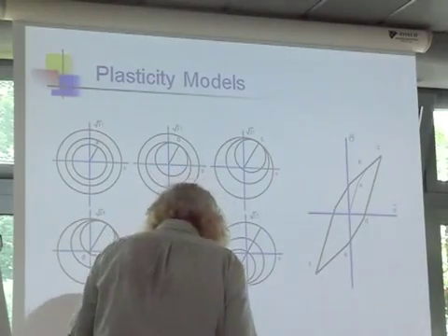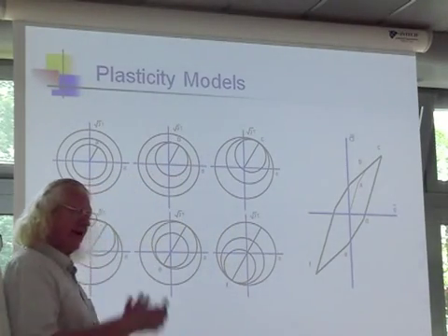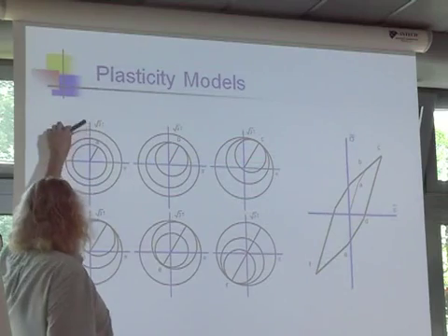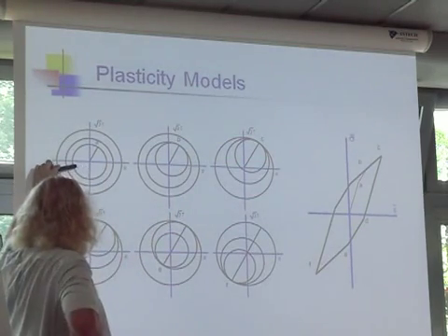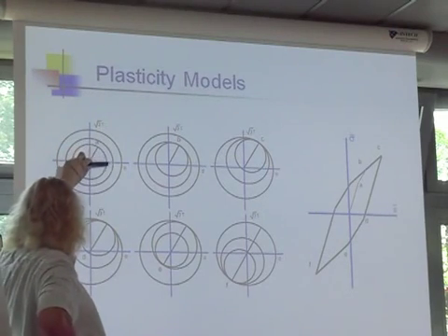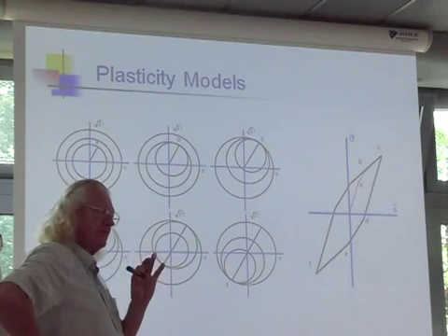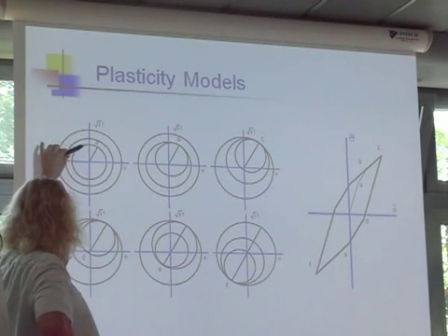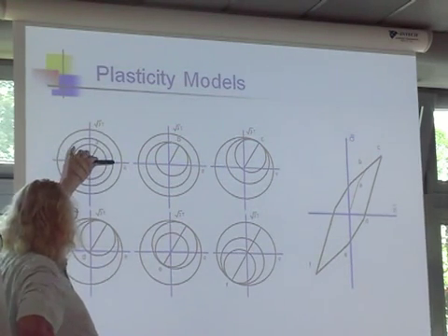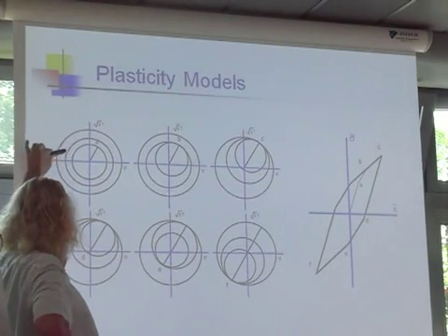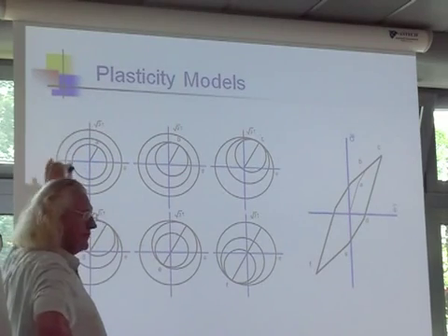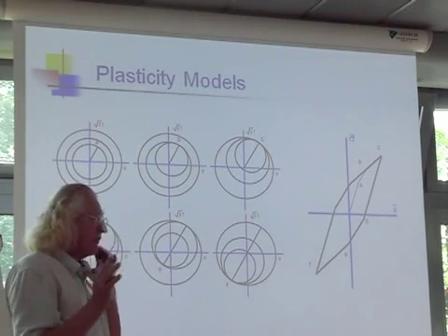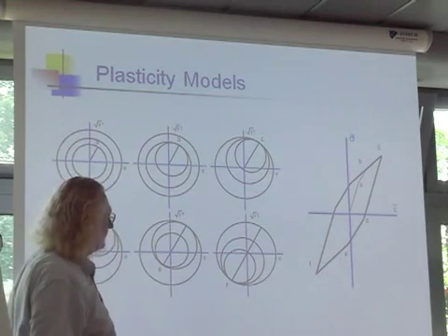So now think about, I have the material. And now I talked about yield surfaces, but I could have these funny little surfaces. Remember, this is just the tension stress, and this is the shear stress acting on the plane. And this represents the combination of stresses that are required to yield the material. But the yield surface concept works for other strains. So for example, this is the combination of stresses that cause initial yielding. This is the combination of stresses that result in 1% strain. And this is all the combination of stresses that result in 2% strain. There's no problem doing that at all. So I don't have to use Mises criteria and restrict this only for elastic behavior. So that's how the material starts.